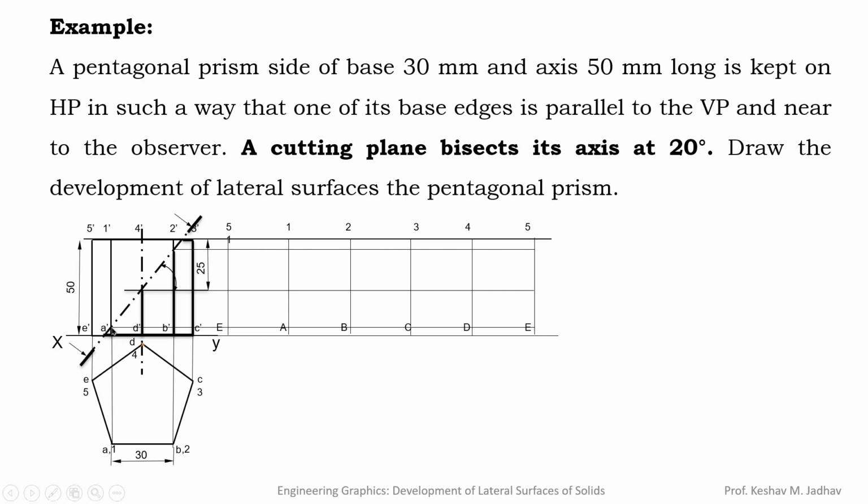So here this line is A1. So on this line we can locate that point. So D4 edge will intersect at this point, so we can locate D4 point here. Then B2. So on this B2 we can get the projection here, so we can locate that point here. So these 3 points we can locate similar to previous case, but how to locate the points at top surface